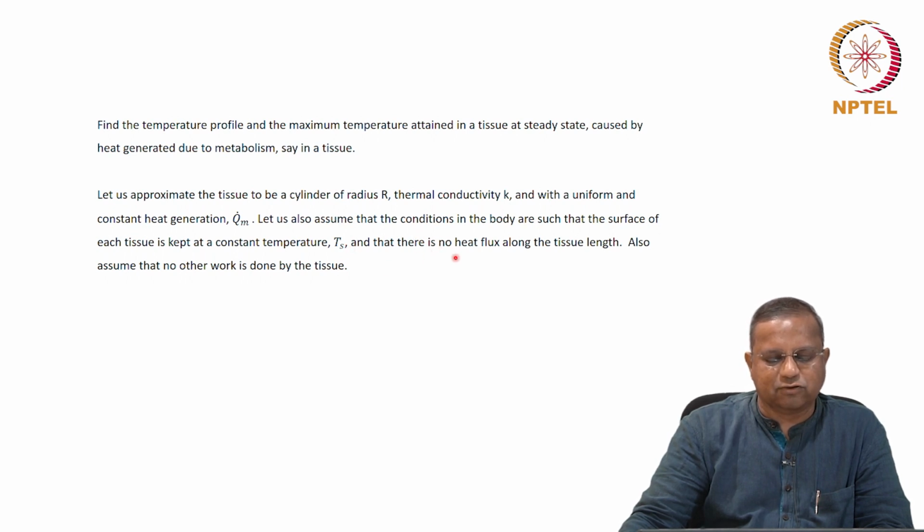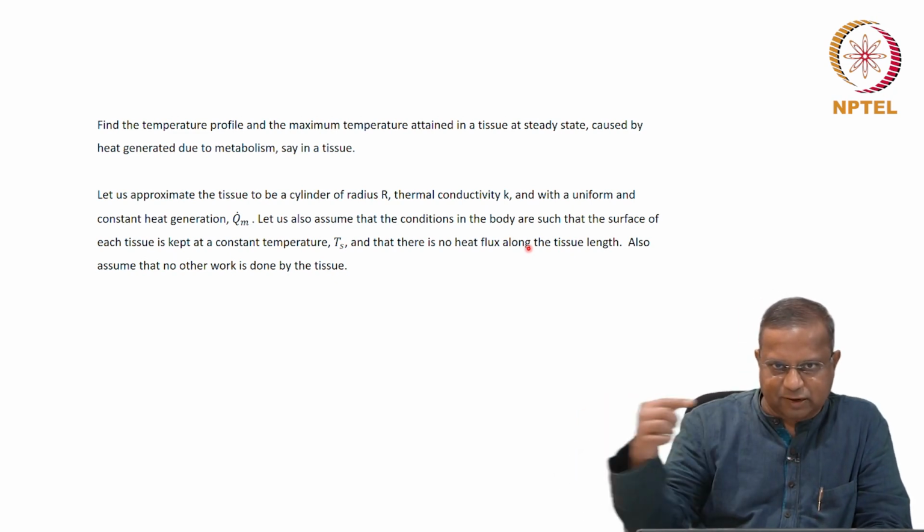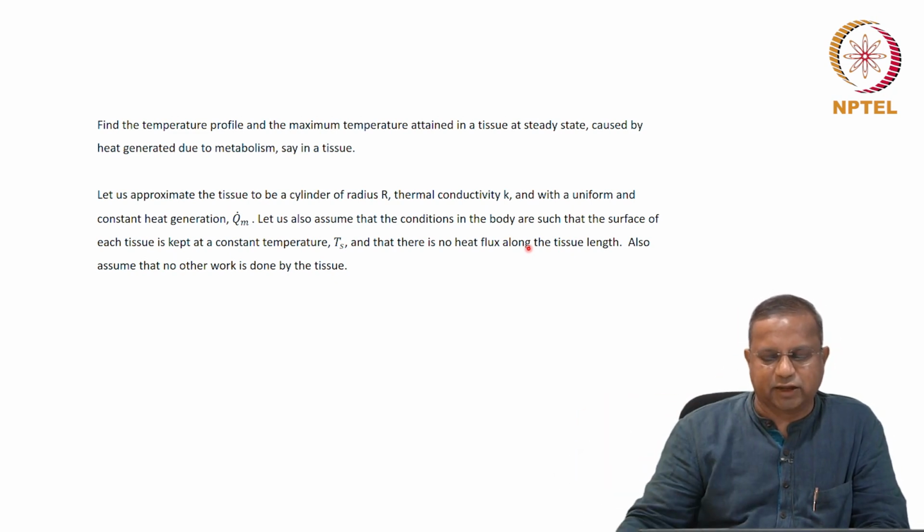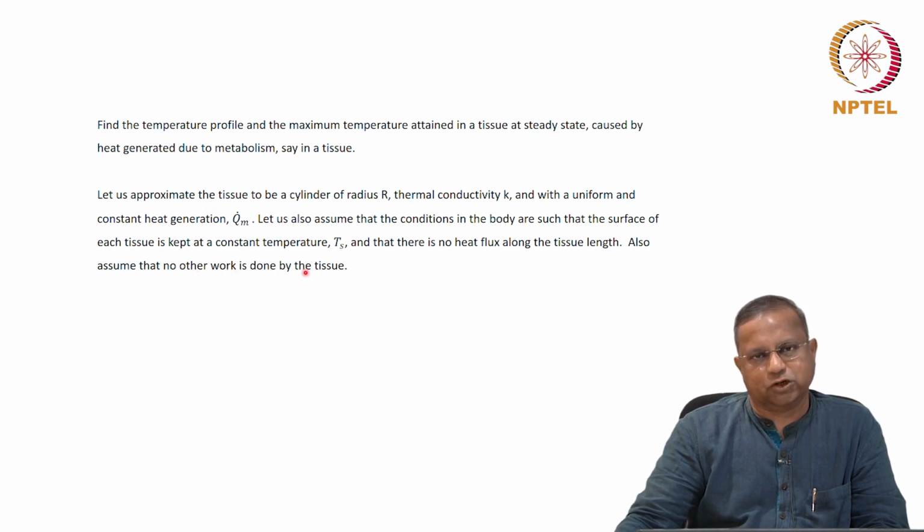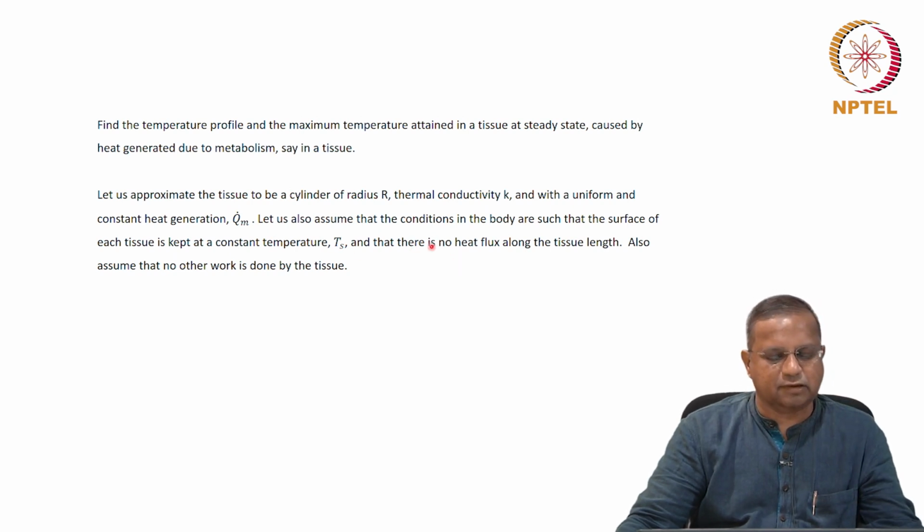And that there is no heat flux along the tissue length. There is no axial heat flux. There is only a radial heat flux. Also assume that no other work is done by the tissue. The tissue is at rest. There is no other work. There are just the other aspects that are associated with the normal functioning of the tissue, in this case, a muscular tissue.